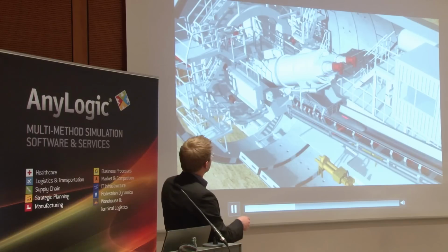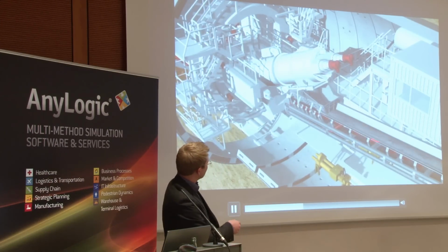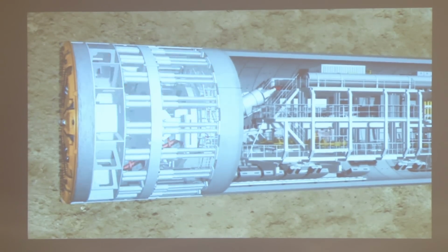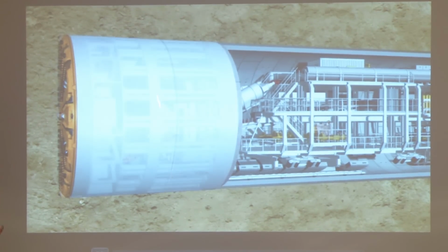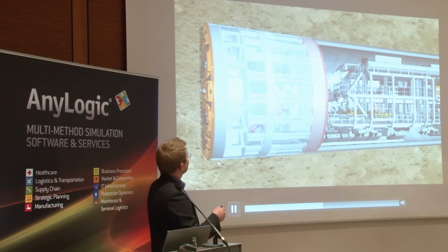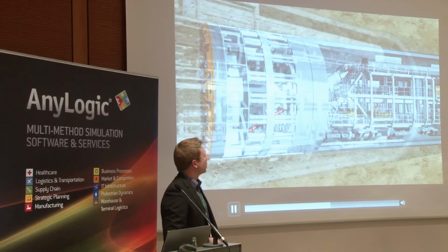It's then propagated to a conveyor belt. We see here a continuous flow of soil. After a certain length, excavation stops, and in the protection of the shield, there's a steel shield around the machine. In this protection, then the actual tunnel is installed. There's a ring installed there.